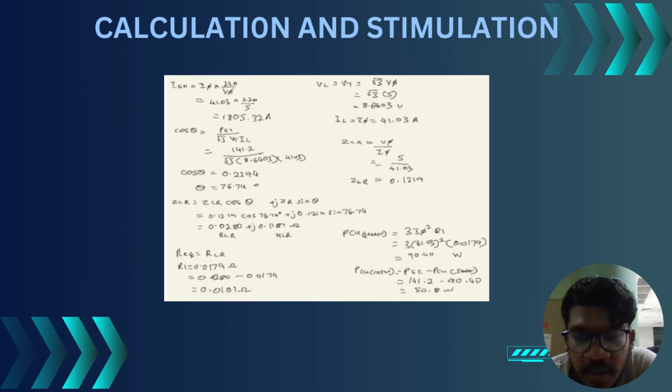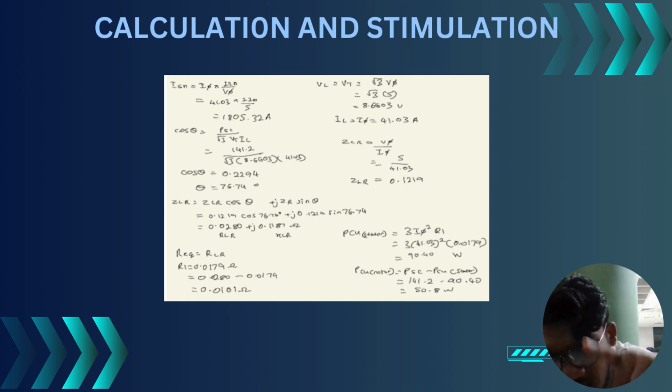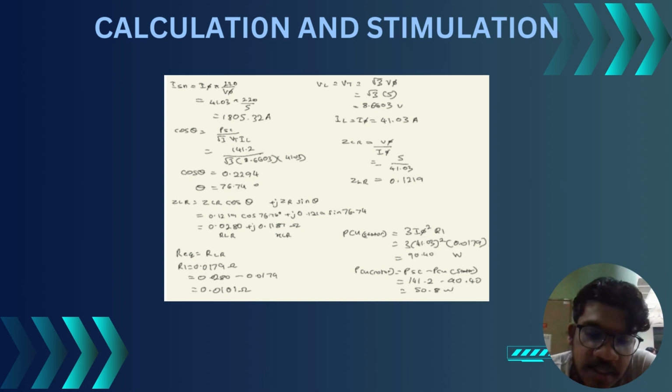the 0.1219 ohm. And then the complex impedance we already see 0.0280 plus j0.1187 ohm. And then the phase angle of approximately 76.74 theta value. The input power increases quadratically with the voltage, and then the power distribution confirms the linear increase in both the stator and the rotor copper losses, indicating the successful verification of the balanced three phase operation.